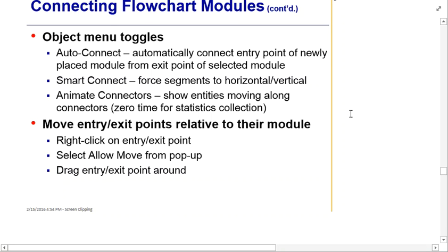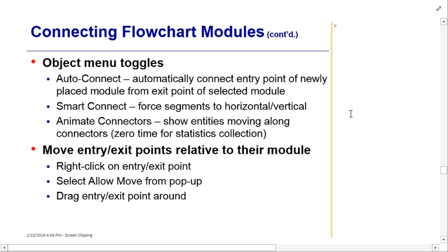And again, it's just connecting the entry and exit points of successive, or, well, not necessarily successive modules. They wouldn't have to be. They could be any modules within the system. You can have a loop, like a reject loop or a rework loop rather, that would connect an output of one module, could be a Decide module, for example, up to something back up in the system, even 3 or 4 layers back, to rework an entity that may have a defect to it.